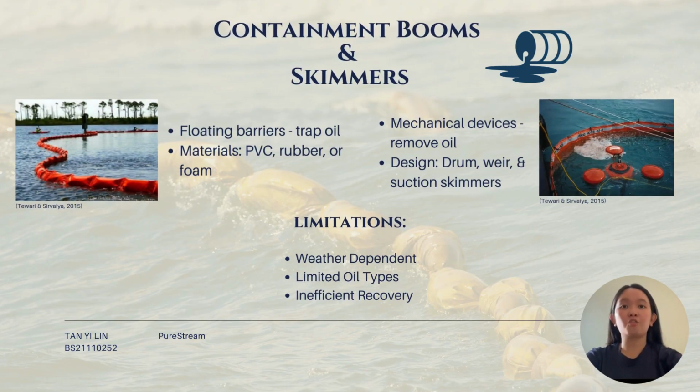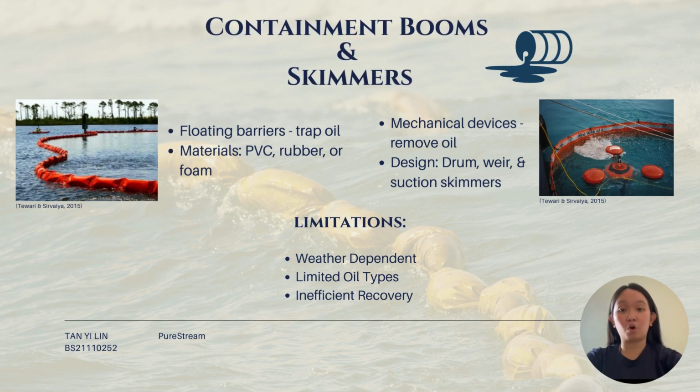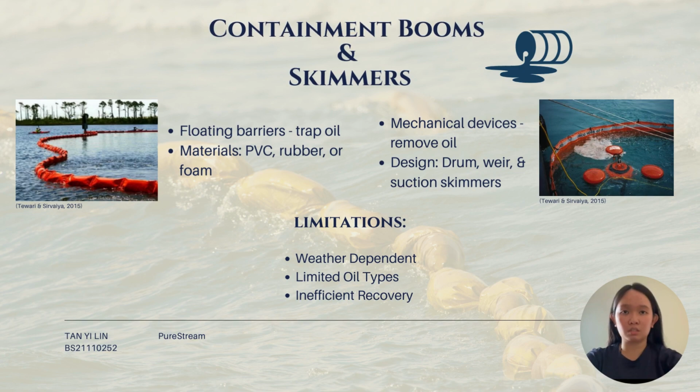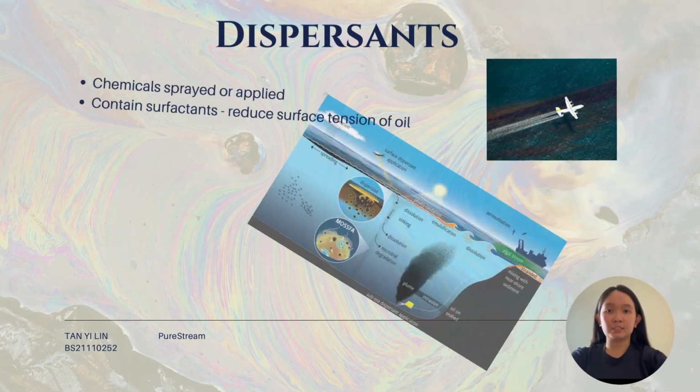Containment booms and skimmers, for instance, are highly dependent on weather conditions and are often ineffective in rough seas or strong currents. Skimmers can also struggle with certain types of oils, especially those that are viscous or mixed with debris, making complete oil removal challenging and leaving residual oil behind.